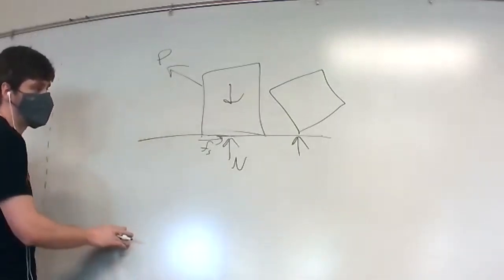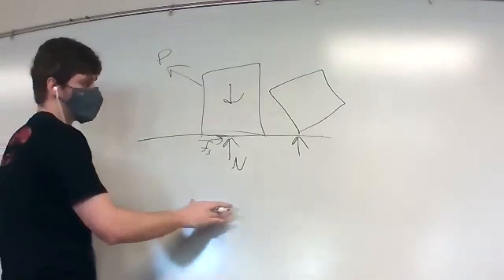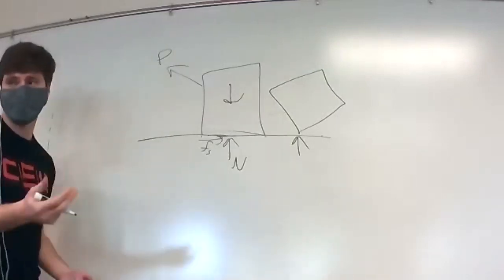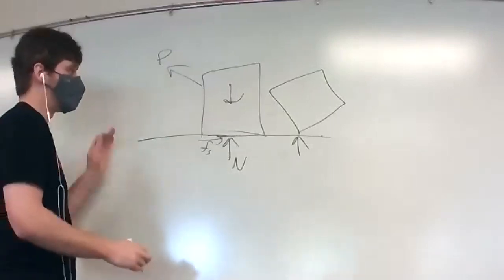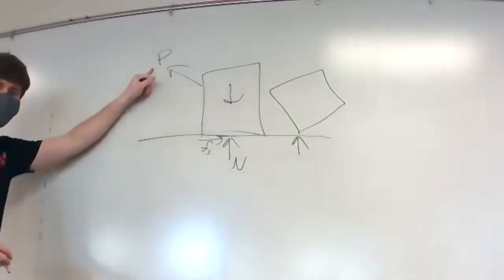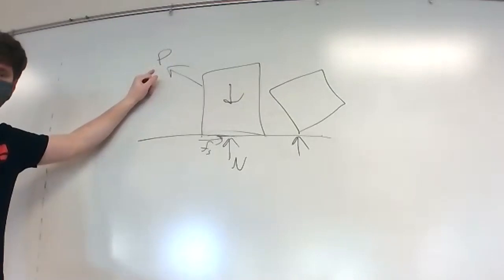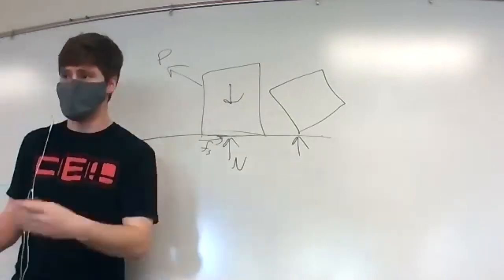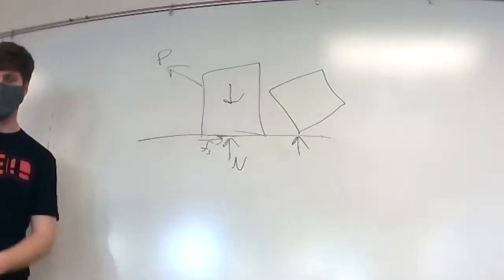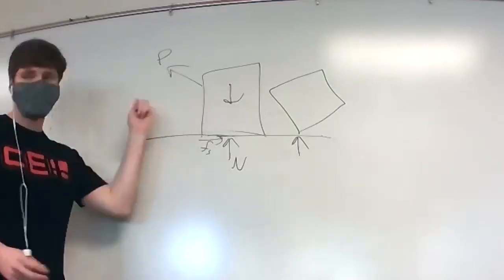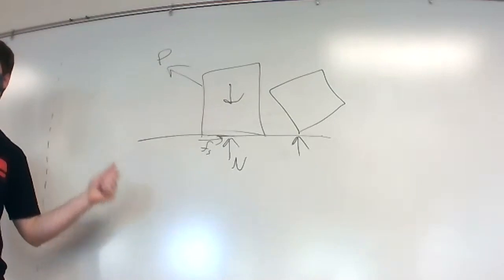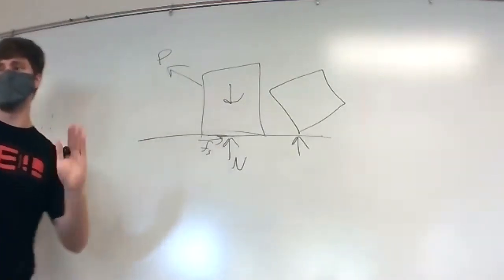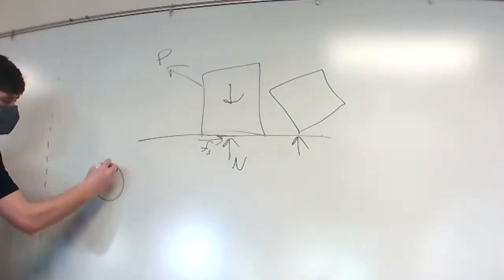You would then solve your equation with whatever you can find appropriately, sum of forces on y, sum of forces on x. You would compare the two different force values you get for slipping and tipping, and whichever one is lower is the one that will cause impending motion first. And when you're doing belt friction, that same lower one is the one that you use when finding the value on the other side, right?